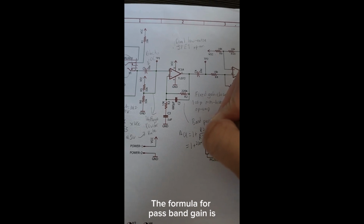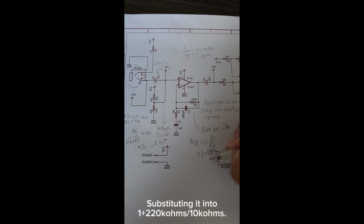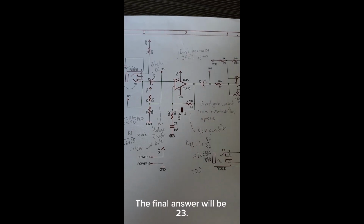The formula for passband gain is ACL equals 1 plus R2 over R3, substituting it into 1 plus 220 kΩ over 10 kΩ. The final answer will be equal to 23.